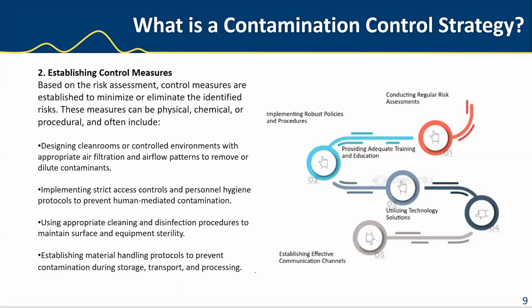So you want to have all this process in the design of your clean room, the control of your environments, implementing strict access controls and personal hygiene protocols, even the awareness of clean room behavior, how to act in a clean room, what to do, what not to do, using appropriate cleaning and disinfection procedures, establishing material handling protocols. So what you're bringing in to the clean room is really important. So these are all part of your strategy,